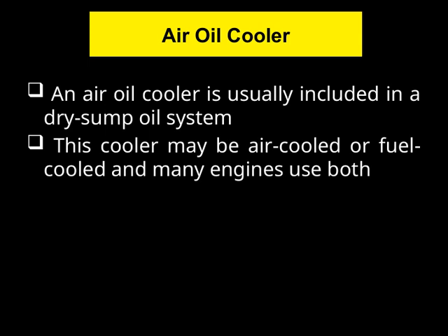This component is essential because it ensures the oil remains at an optimal temperature for proper lubrication and engine performance. Now, this cooler can be either air-cooled or fuel-cooled, depending on the engine design and cooling requirements. In fact, many engines actually use both types of coolers to maximize efficiency and maintain consistent oil temperatures. The air-cooled oil cooler relies on airflow to dissipate heat, making it a simple and reliable solution.